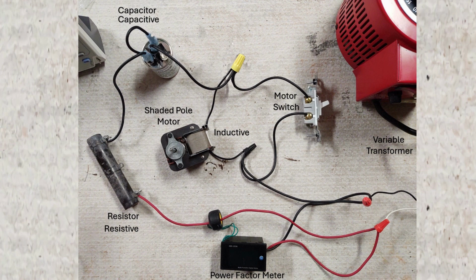Here you see a switch wired in parallel with the motor. Normally, switches are wired in series with the load they control, not in parallel. That would not work in this case because opening a switch wired in a series circuit would shut off the entire circuit. The switch wired in parallel removes the motor from the circuit by shorting across it. Current will not flow through the motor with no voltage difference across the motor.